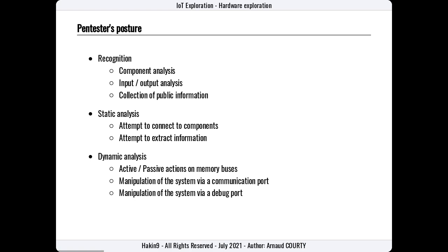For example, getting the manufacturer and the version can guide you to the corresponding datasheets, knowing the correct voltage to avoid frying the board during your investigations. From deeper internet research, maybe some hidden commands will be available and speed up your investigation.